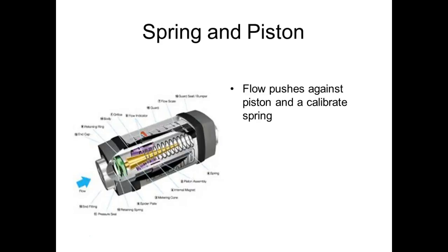So when we move this, the magnet is going to cause, or whatever we're sensing out there. If we want to do it electrically, then our transducer would be like a Hall effect, right? You understand? If we wanted to do it digitally, then we might have a reed switch out there. And when the reed switch hits a certain point, it would give us a signal that the flow is okay or not okay, right?